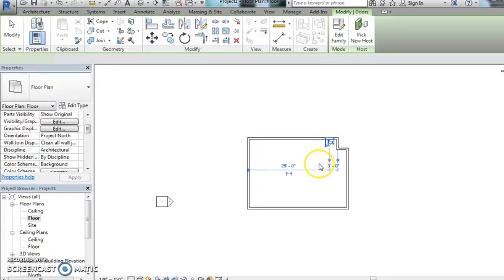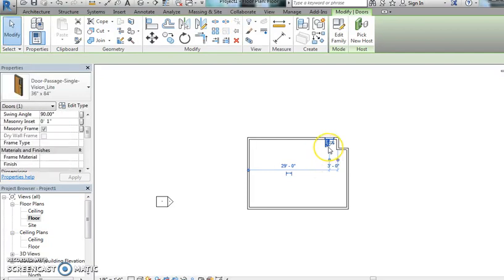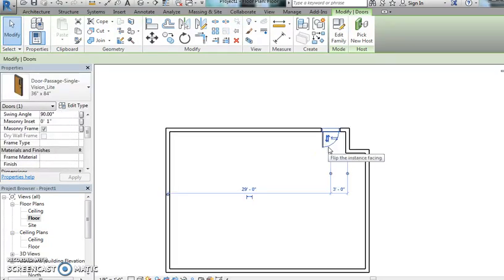Okay, you click on the door you just installed. You've got two arrows. I'm going to scroll in so you can see that better. Okay, flip the instant facing. So it actually opens on the outside of the room. I click that, and then it opens towards Miss Hagedorn, not Miss Popham. So to change that, I'm going to click these arrows, the ones that are going horizontal. And again, my laptop's taking forever to load. So now we have the door opening the proper way.